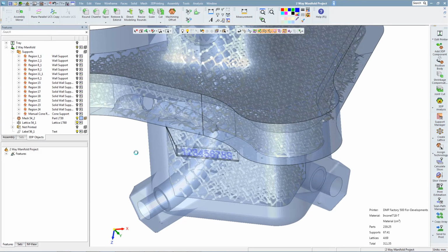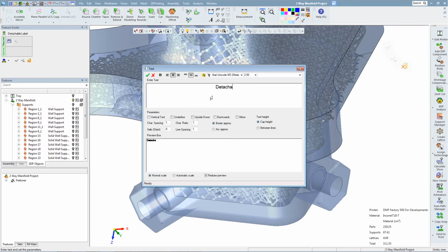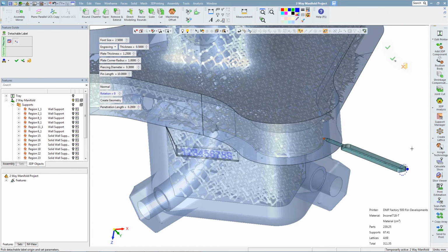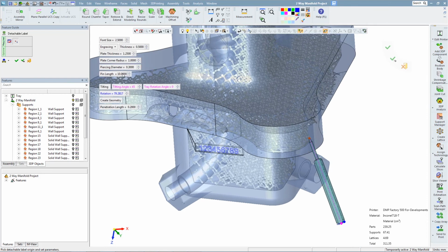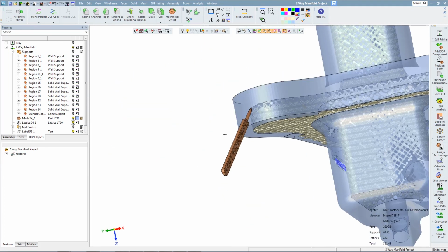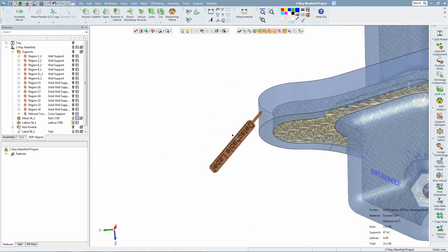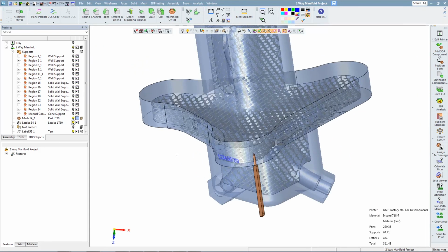Please ignore this small meshing artifact. We can also create a detachable label, which is useful for small parts or cases where we don't want the label to stay on the part. We can control the size of the detachable label, its distance from the part, its angle, and so on. In this case, we chose to create the text as actual geometry, but we can create it as symbolic text as we did with the label. As I said, we will get back to smart labeling and see what we can do with this symbolic text when we deal with tray arrangement.